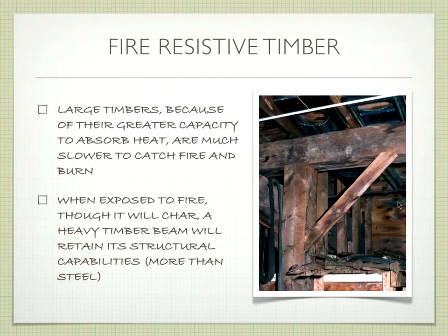So the interesting thing about heavy timber frame construction is that it's considered to be a fire-resistant material. If you have a big 8x8 or a 6x10 beam, and it's exposed to fire, the outside is going to char. But because there's so much material to it, it's going to be really hard for the fire to actually burn through and weaken that beam enough to fail.